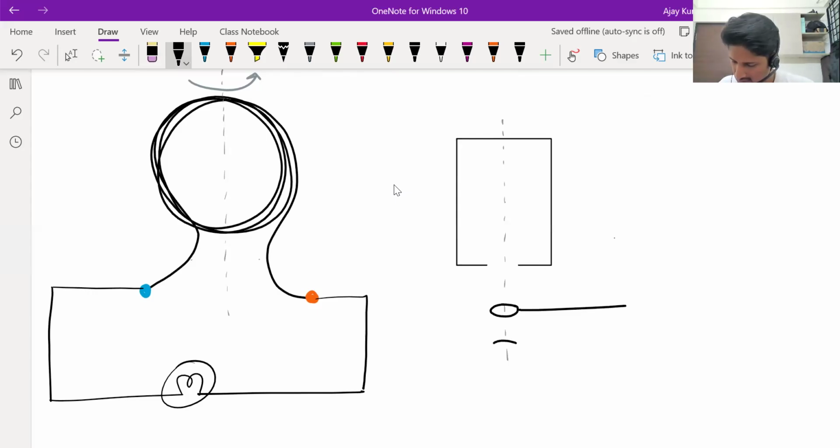There's another ring here that is also connected to the circuit. Now, one end of this coil, you make it touch this ring, just touch, it's not rigidly attached. So as the coil rotates, this point of contact keeps sliding along this ring. It keeps going around.